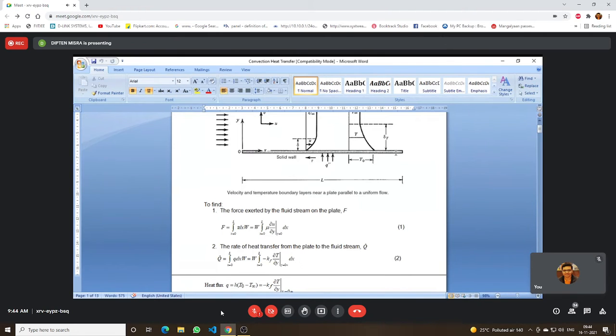That is why we are avoiding the solid domain. We are just taking the solid as a bounding surface where the temperature is known. And what we are trying to concentrate on is the fluid domain, where we are trying to find out the temperature solution, the temperature gradient solution, and taking a boundary condition as T is equal to T0 at Y is equal to 0.